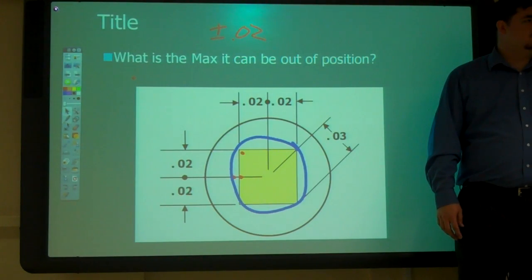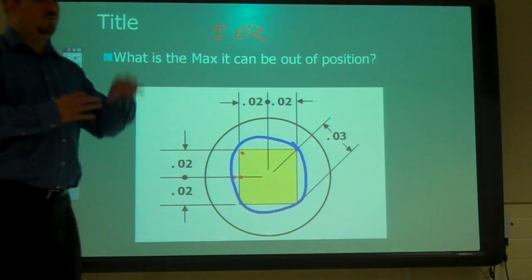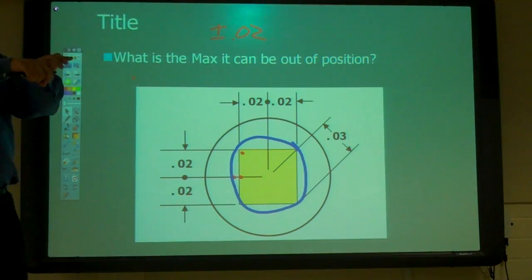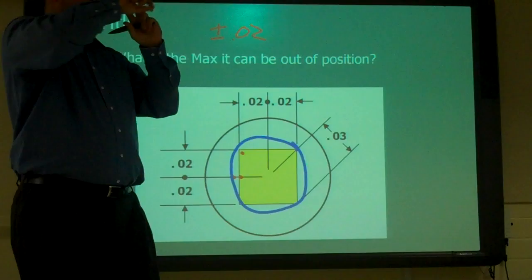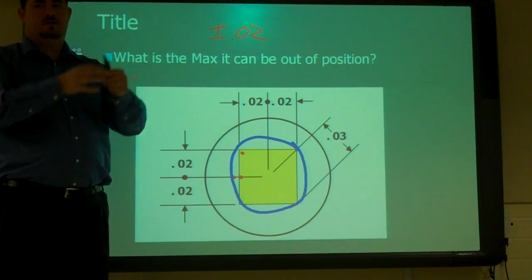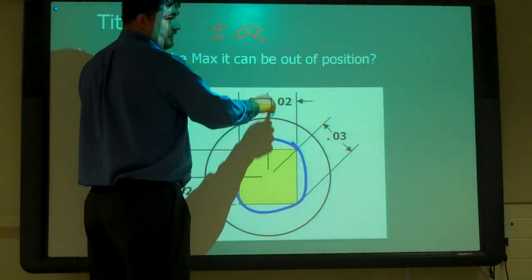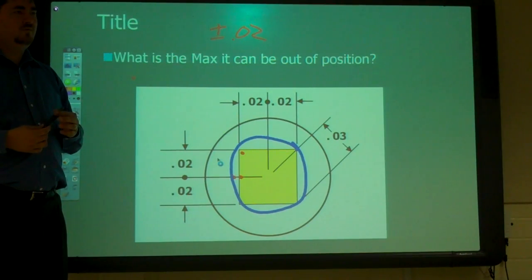If you were talking about drilling a hole in the end of a part that rotated, say, a camshaft, is it possible that your target area instead of being a circle would be an oval because you want it to go more one direction versus the other? But what is that lining up with? With another hole? Usually you'd want it to be a circular position zone where that center could be, because you have your perfect alignment, and then the slop around that. So that would make it even worse, because then you could be more out this way than you can be out that way. That really doesn't make a whole lot of sense. Unless you're trying to stay away from having it go out those directions, is what I'm saying.